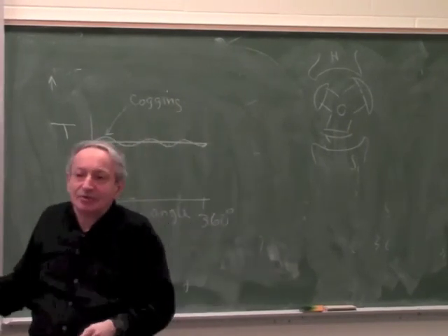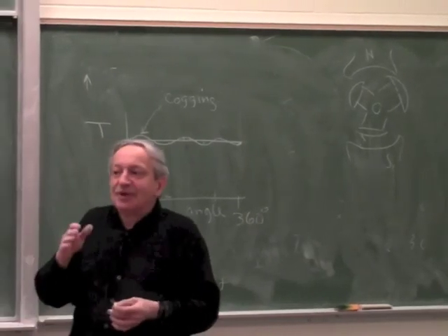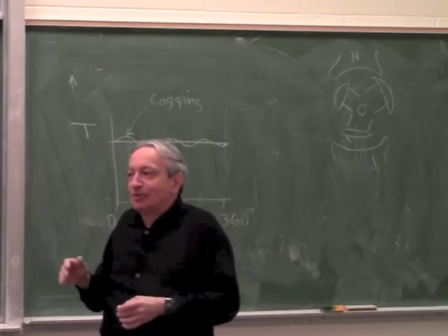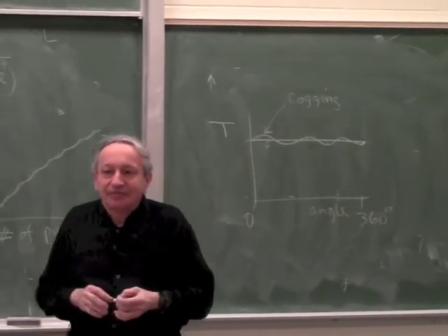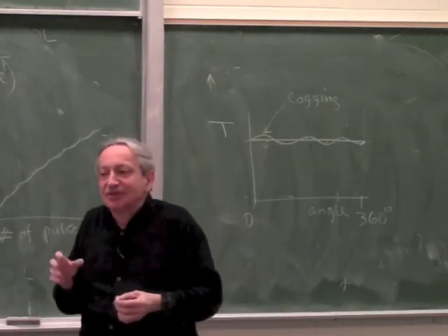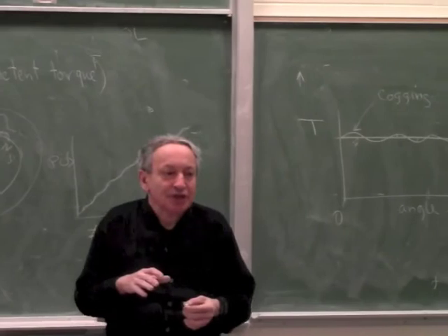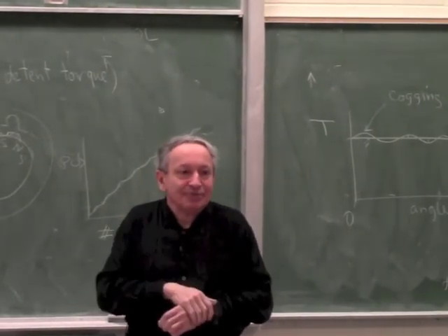In an industrial motor it's never specified because nobody cares. There are a few other things in the spec of a servo motor which don't show up in the spec of a regular motor. For example, the most important thing is the ratio of torque to inertia. Because the ratio of torque to inertia is how fast it can speed up, right?